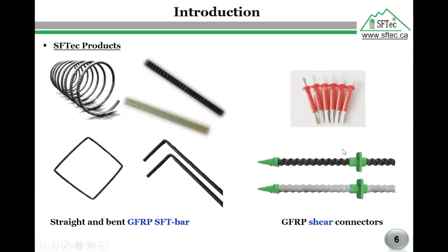In terms of comparison between steel and GFRP connectors, originally we had steel connectors. When comparing the steel one with the GFRP one, the performance is almost the same. Also, in addition to resisting corrosion and longer service life, the structural integrity and stability, all of these issues you can achieve with the GFRP connectors.